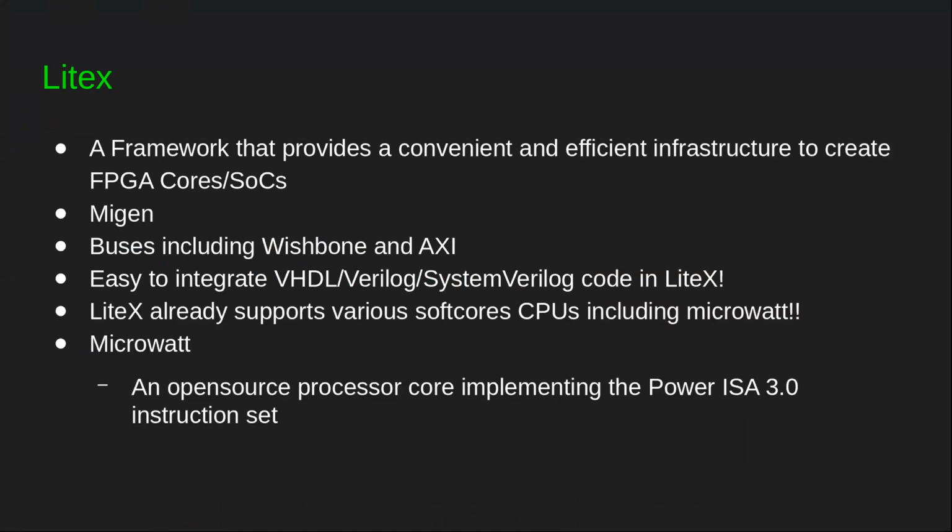It is basically a framework for creating SoCs, and it is based on Migen, which I think was discussed in one of the talks. It supports buses like Wishbone and AXI, and you can integrate your existing VHDL, Verilog, and SystemVerilog code in Litex.